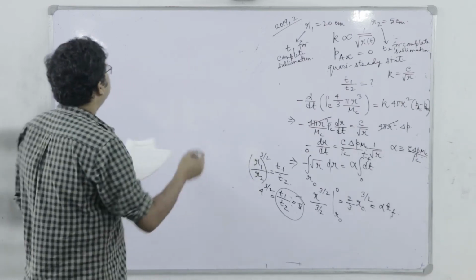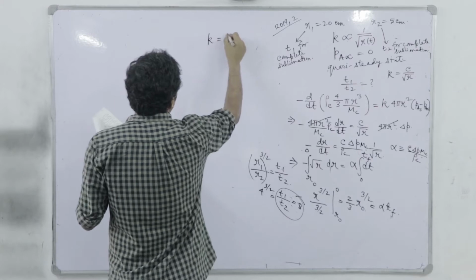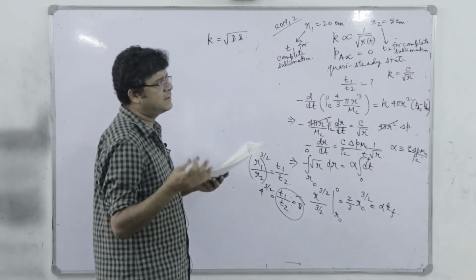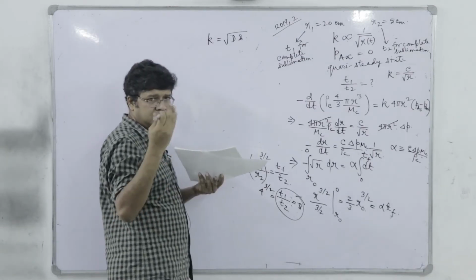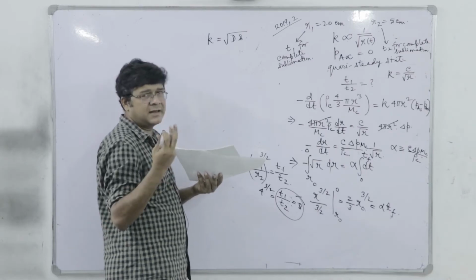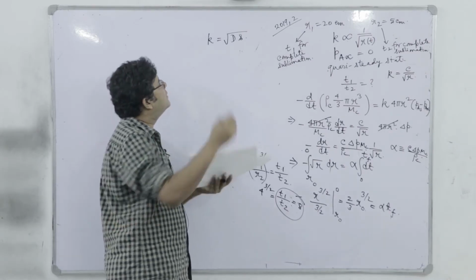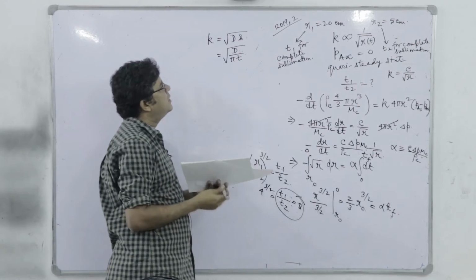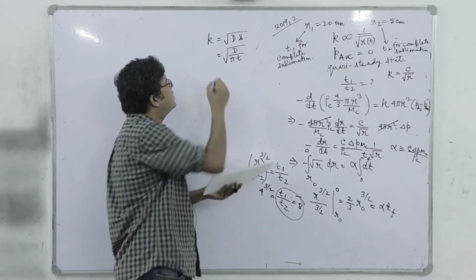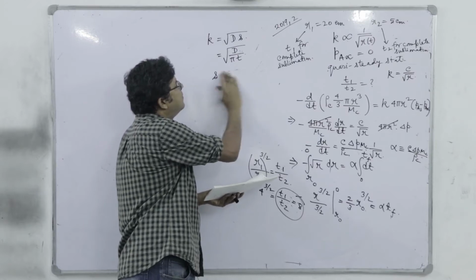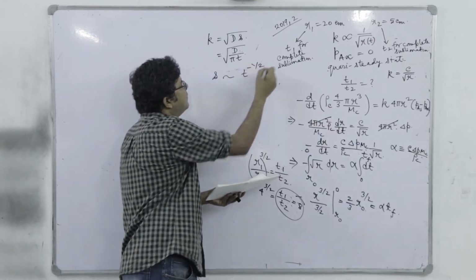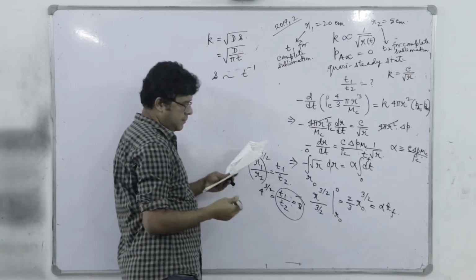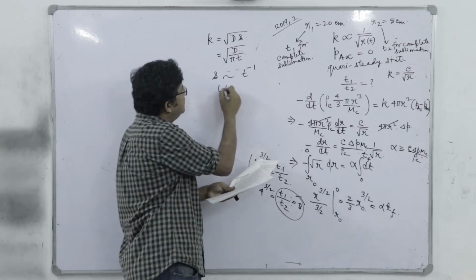So, you see that K is equal to under root of D into S. Surface renewal rate must be in terms of number per second, that's very obvious, because dimensionally it should match with the penetration theory. So, S, the unit, must be in the order of t to the power minus 1. So, the answer is D, second inverse.